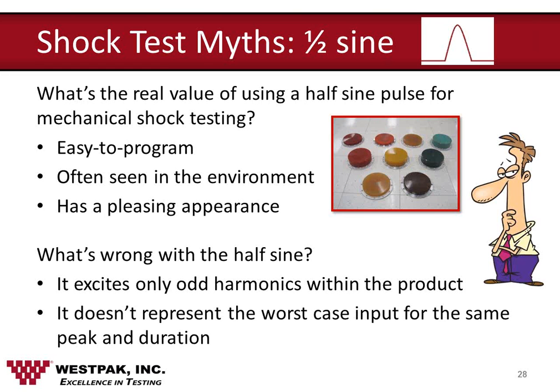There have been reports of people programming the duration of a half sine pulse in order to get into some of those reduced portions of the spectrum, and in order to have a product pass a certain test where it really is not that rugged. So don't think that the half sine is the be-all and end-all.